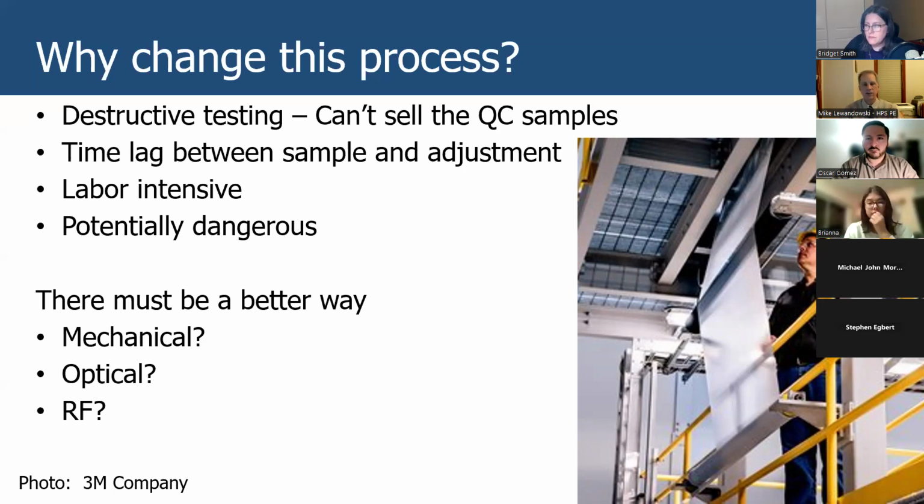And then you take another sample and you go back to the laboratory and you cut the sample, you make your measurements, compare to the tolerances, provide feedback back to the manufacturing line, and you do this all day long. So you end up with large swings in your behavior of the thickness until you finally dial that in, and then you get the machine working just right, producing exactly what you want.